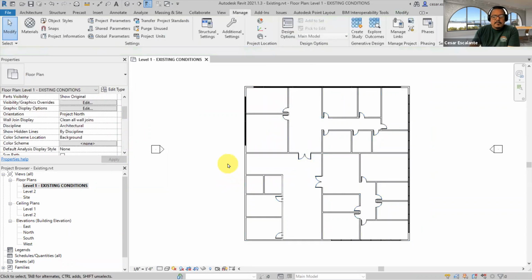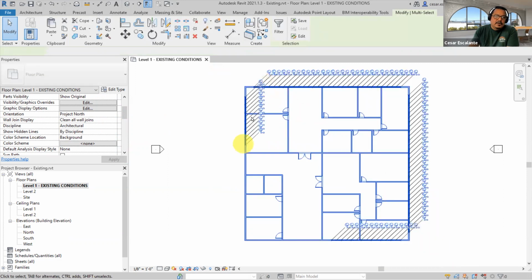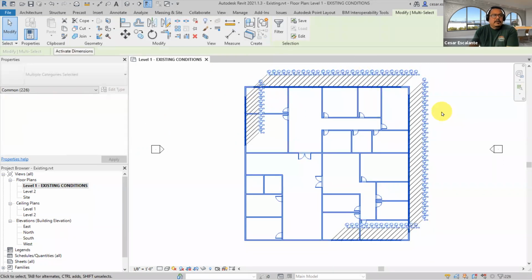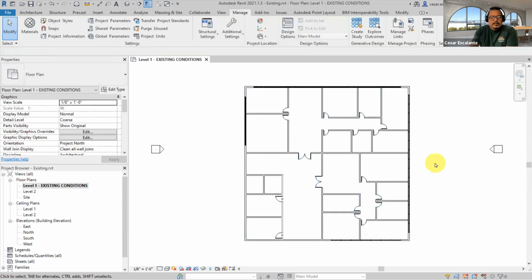Let's see. I'm going to disable Revit's selection of pinned objects. Notice when I do this, you see all those pins. Those are curtain panels, and the curtain panels inherit the phasing of their host. And so there's no need to select them or change phasing at all. So I'm going to disable our ability to select pinned objects. And I'm going to do this again.